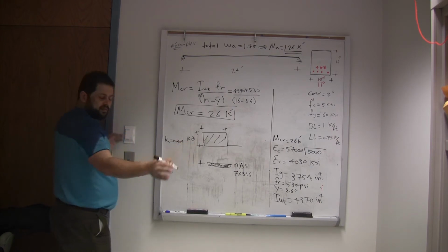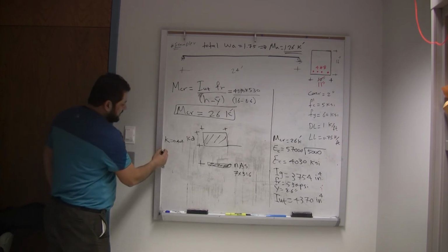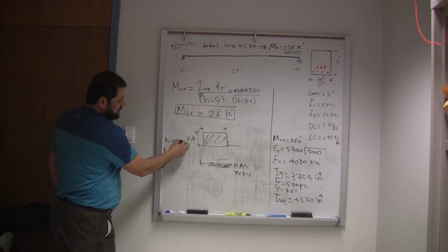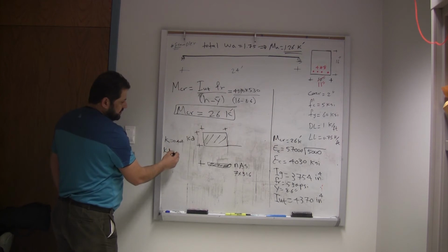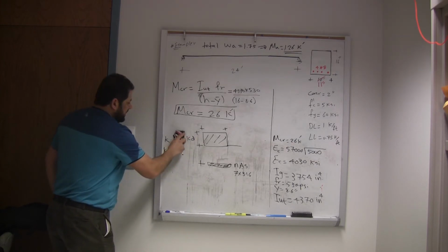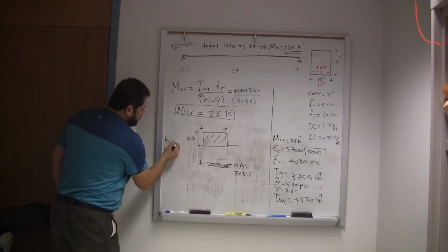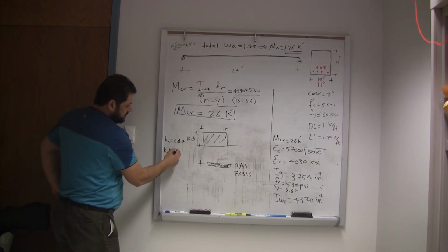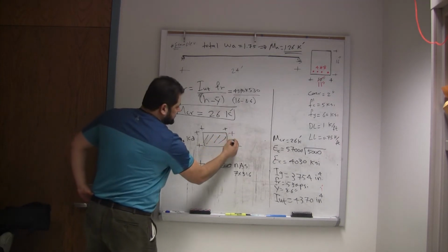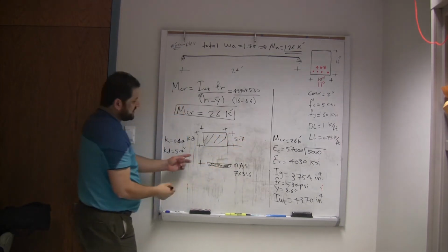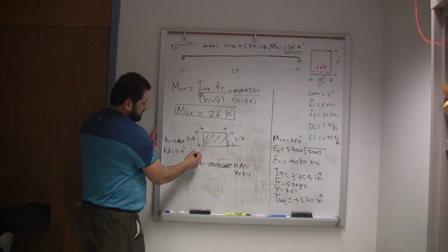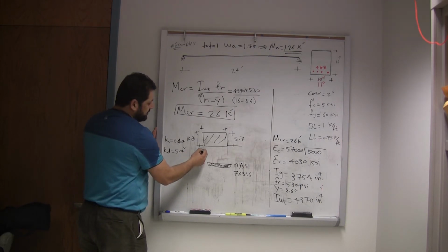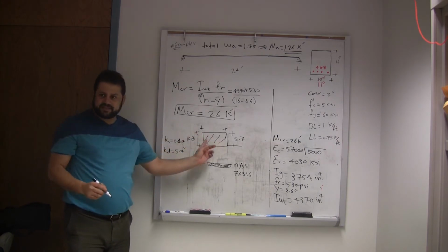Or calculate it from the formula. So KD is what now? It's 0.407 times 14. Guys, just for you to clarify it, K is 0.407. So KD is 5.7 inch. So this distance is 5.7. If this is 5.7, 14 minus 5.7 is 8.3. Right?